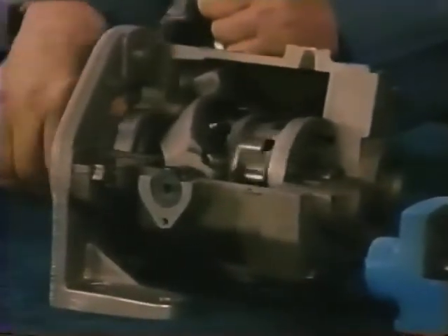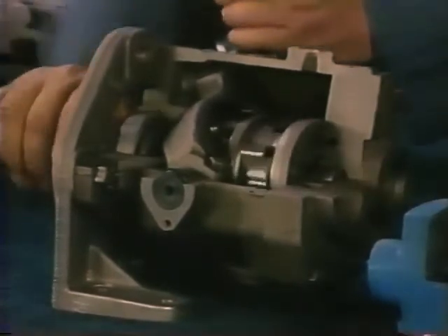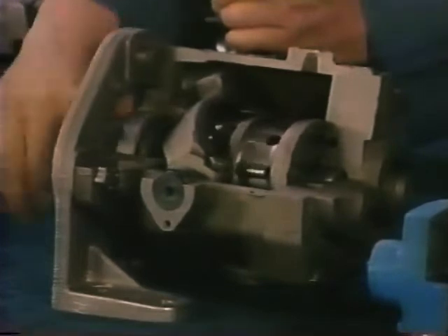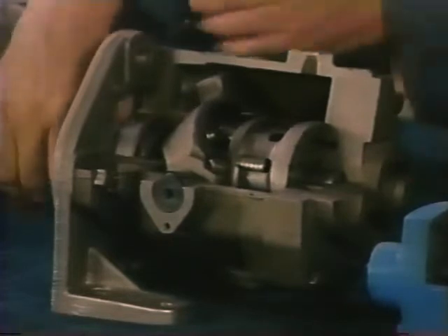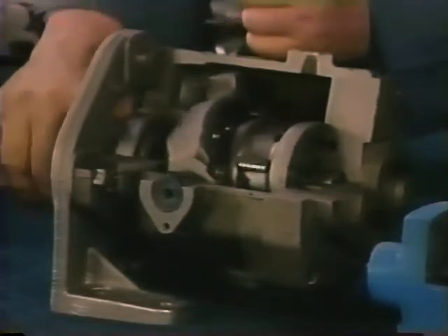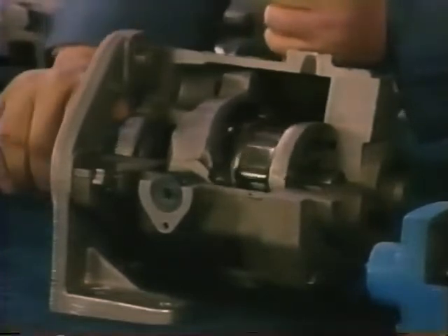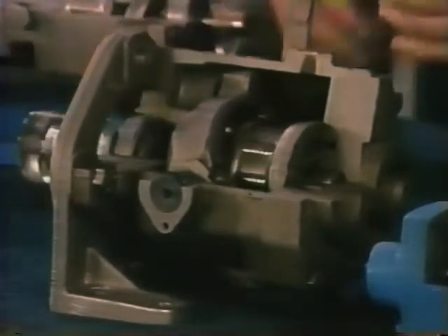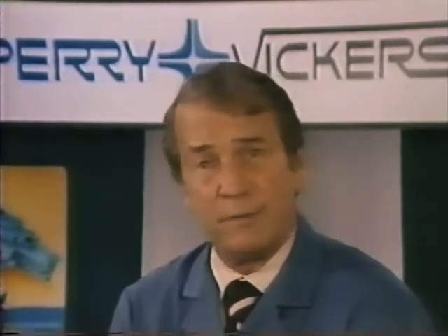As they come out, oil enters here, making this the inlet port. Pistons on the opposite side are being pushed in by the swash plate, and oil is forced out of this port. Notice how the piston movement is decreased as the lever is moved towards center. Centering the lever puts the yoke and the swash plate at right angles to the shaft, and the pistons cannot move in or out. Now, if we continue to rotate the drive shaft in the same direction, but move the lever across center, the piston movement and oil flow is reversed.